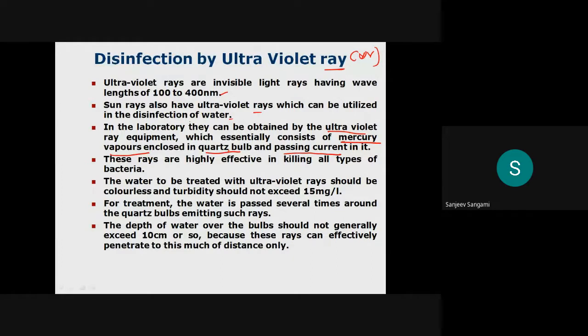These rays are highly effective in killing all types of bacteria. The water to be treated with ultraviolet rays should be colorless, and the solids should not exceed 15 milligram per liter. The turbidity unit is NTU.